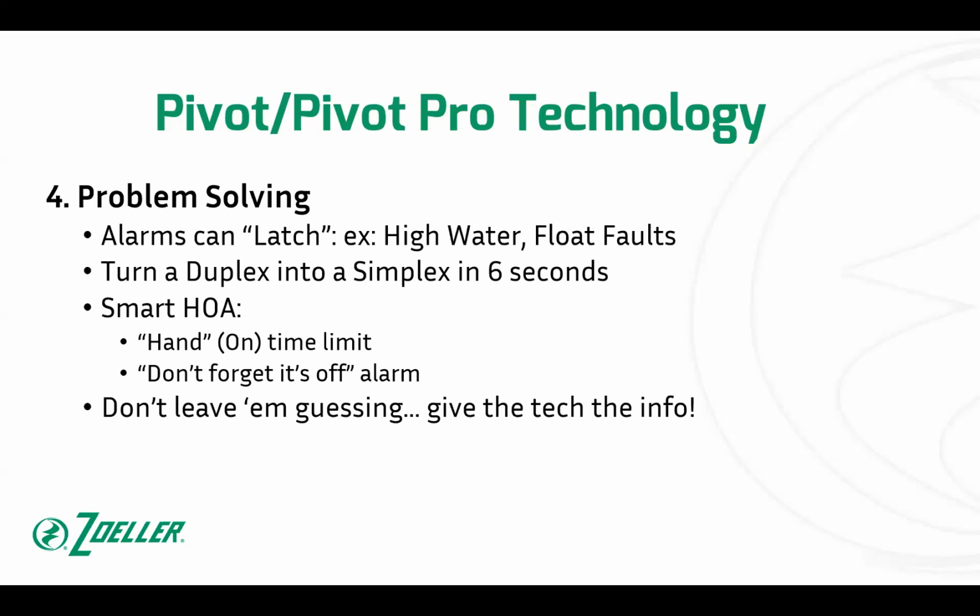Smart HOA. HOA is hand-off-auto. If I put a pump into hand, I may accidentally forget I put it in hand and walk away or go to lunch or whatever, but now I'm not burning out a pump because that hand has a time limit. Default is 5 minutes. You can make it whatever you want, but we're saving pumps now from being burned out, and then the contractor comes back and his mistake now becomes embarrassment, and there's a cover up that ensues. So let's avoid that altogether and just put a time limit on it. If he needs to run it again for 5 more minutes, he just pushes the button again. It's real simple.